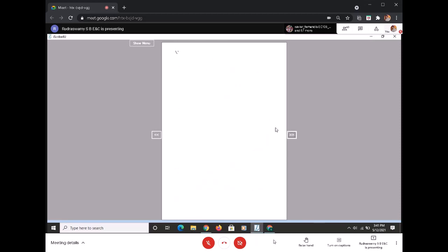First, the NOR based SR latch, and make sure that all the different types of flip-flops are based on the SR latch. The SR latch forms the basis for constructing any of the other flip-flops like the D flip-flop, the T flip-flop, the JK flip-flop and all.